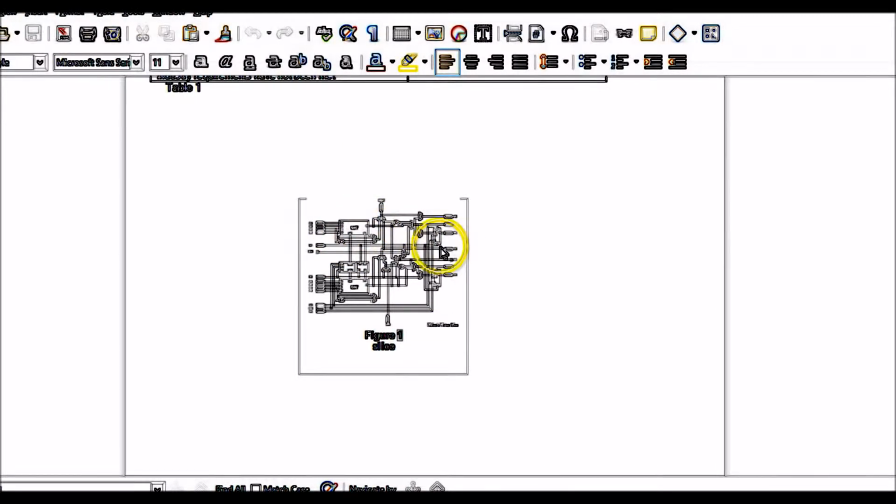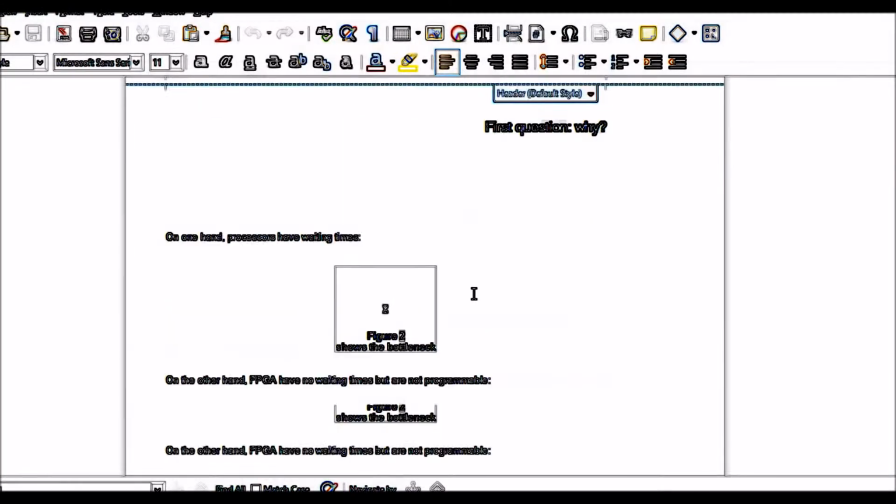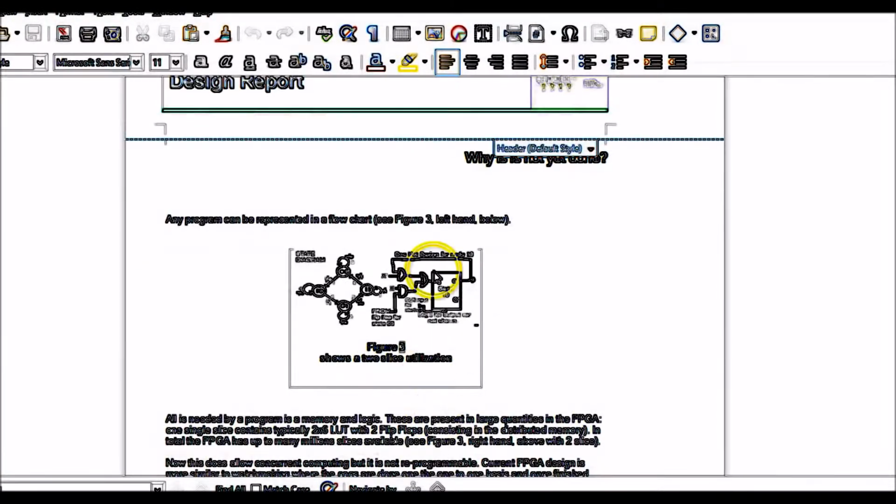In the FPGA, the smallest unit, the slice, is actually made up of one lookup table for the logic and a flip-flop or storage register that can correspond to one state of a state machine as seen before. The FPGA have up to millions of these slices that can run in parallel. Using this method is optimal because in effect one can have up to 1 million states defined that are like little programs that can run concurrently, like the cogs of a big clockworks.